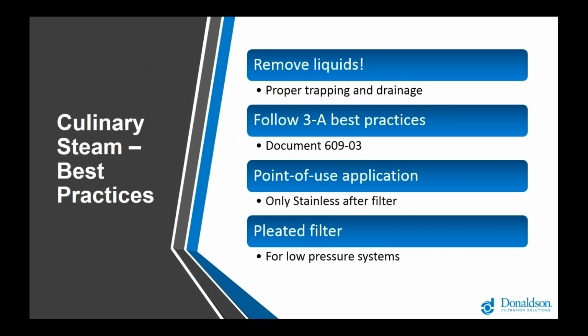So culinary steam best practices. The most important design consideration I've found in these systems is really to ensure proper liquid drainage. So steam is constantly condensing into water as it gives up its heat energy, and as it does this, that very water that produced the steam can turn into its own worst enemy. So the problem with water is that it can create high velocity slugs of liquid within the system that can create very damaging impacts to components like valves or filters, and proper drainage is critical. So every low point in that system needs to have a drain valve.